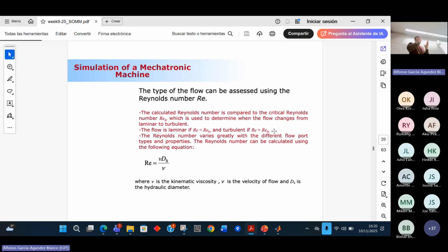So basically, what you need to know related to the Reynolds number is that when you have a low Reynolds number, the viscous forces are dominant, and you will have what? Laminar or turbulent? Do you know? Low Reynolds number is usually associated with laminar, exactly, because if you have a ratio of inertial over viscous forces and the viscous forces are dominant, you will have laminar flow.